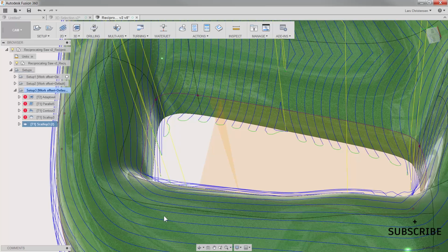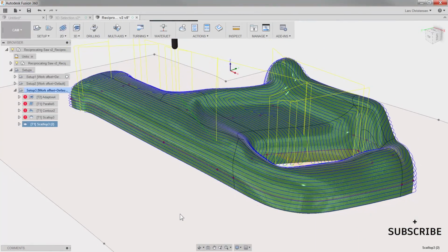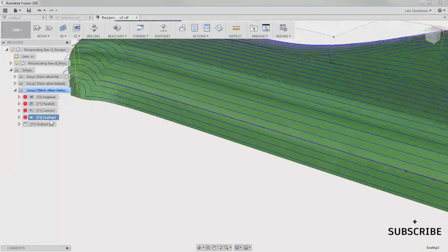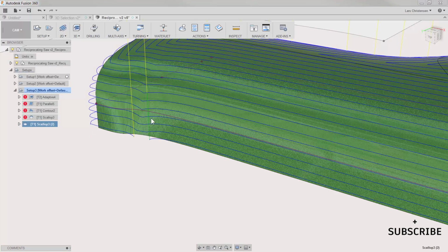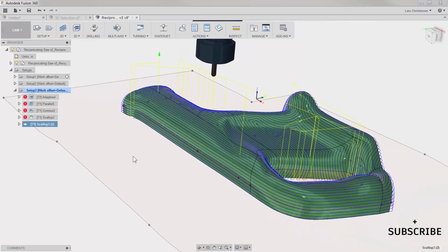So be aware that you can control the scallop toolpath with other geometry, controlling how it's going to collapse in. So just to point back here, we can see this edge here, and when I hit the scallop, you will see that we now got a different one. Now you could change the sketch geometry a little bit, play around with it, and you will get different results. But that's an important thing to know about the scallop toolpath.